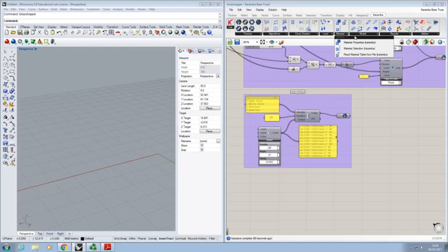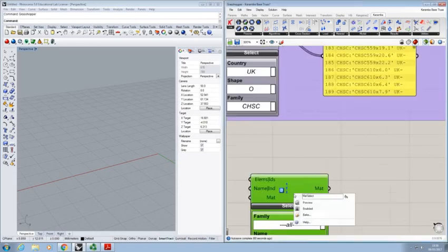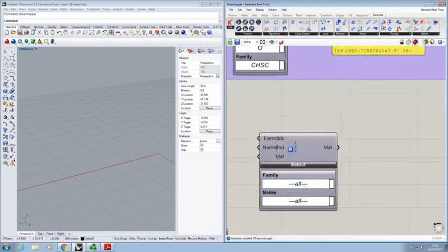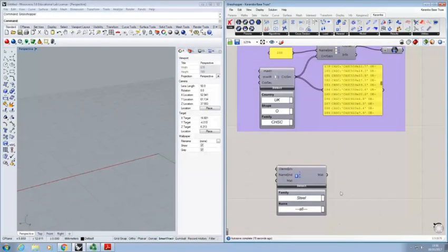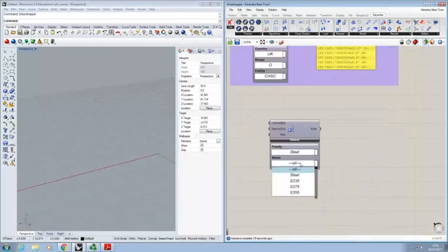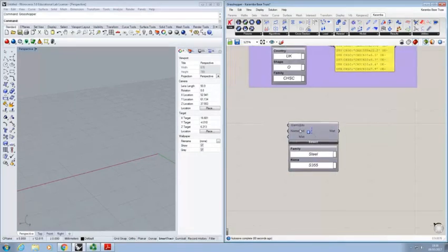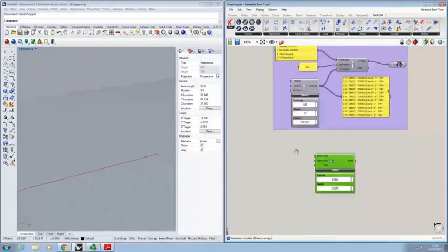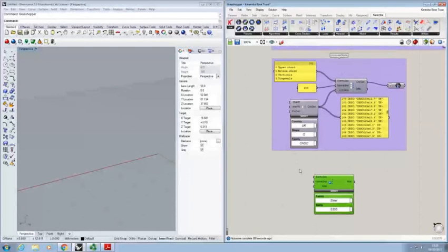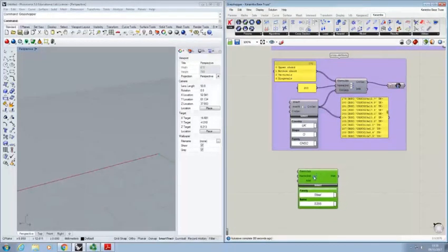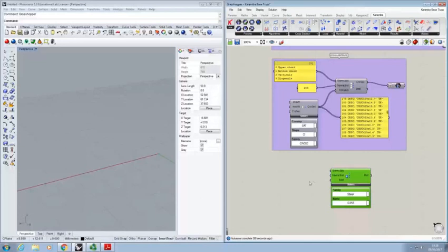So that's the easiest one. Karamba, material selection. If you go in here and click on select, drop down menu, family steel, name, most common steel used these days, S355. And now we need to tell this material component which elements to apply this material to.